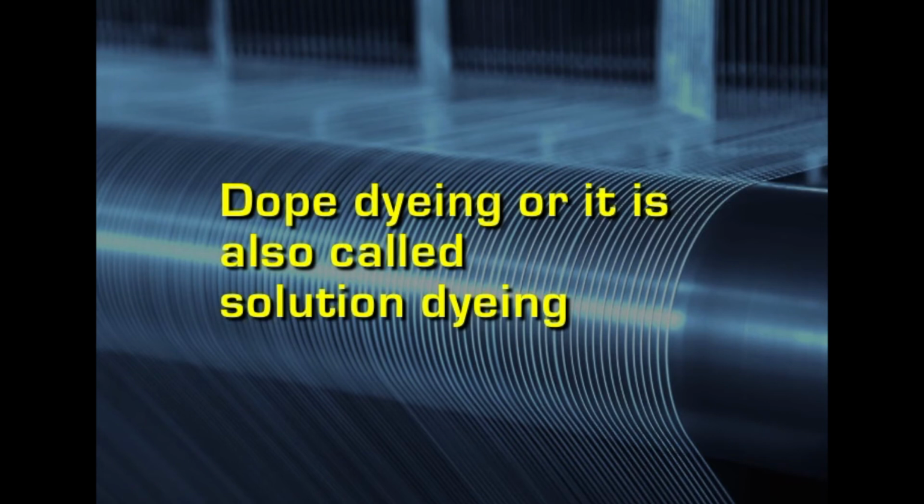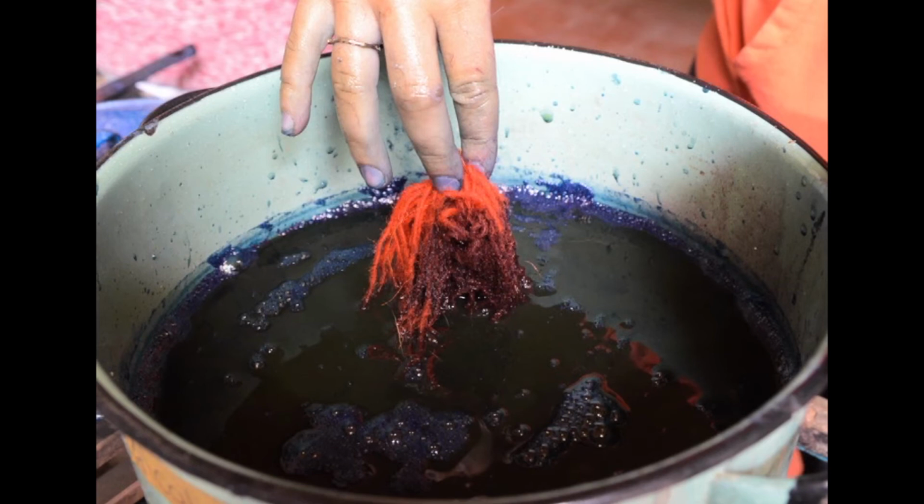all dyed fabrics. Dope dyeing, also called solution dyeing because it is addition of the dye within the solution, is also called solution pigmenting. This is done when a single colored filament is required in large quantities, something like making a khaki material or navy blue material which is being used in large quantities. For production of that, usually this dope dyeing is employed. So you will get a single color, as the whole solution will produce only the filament of that color.